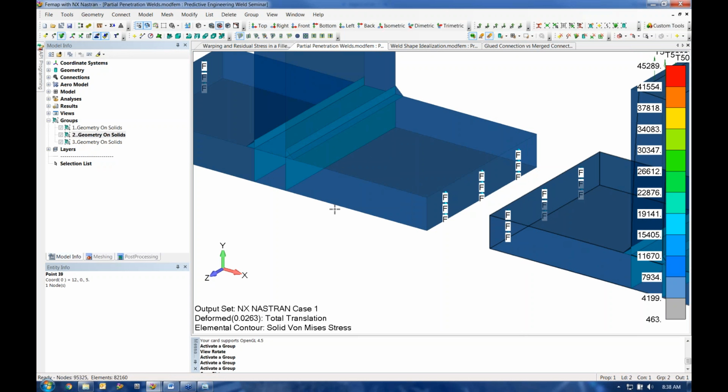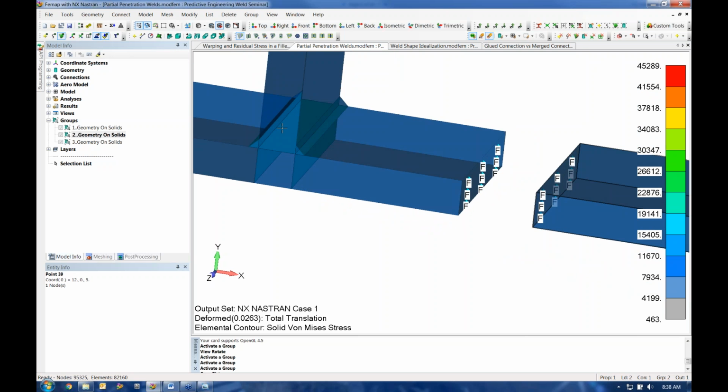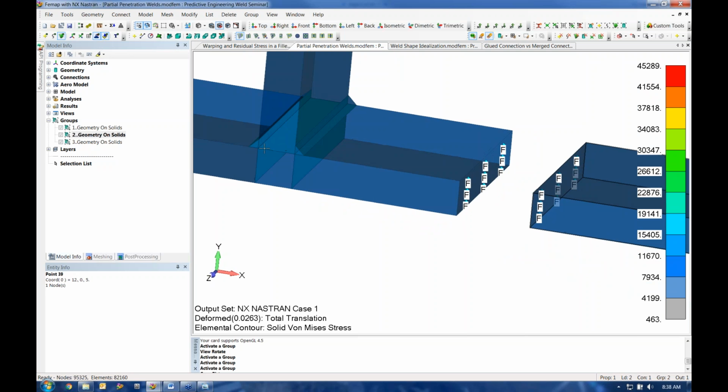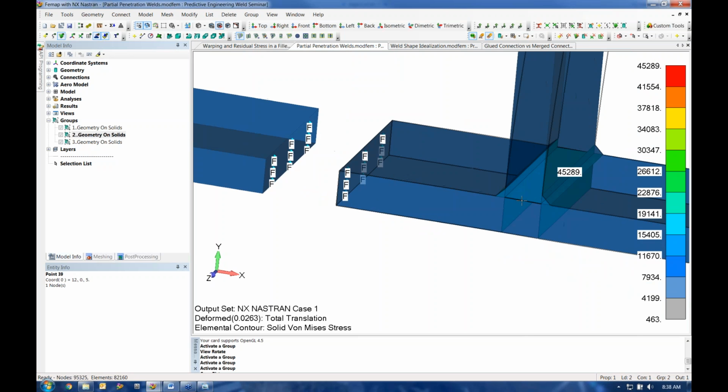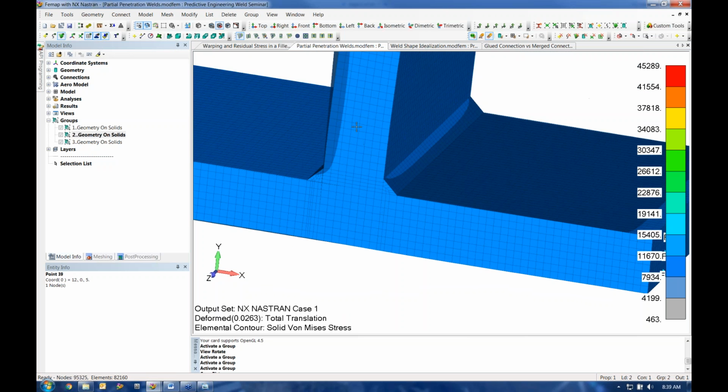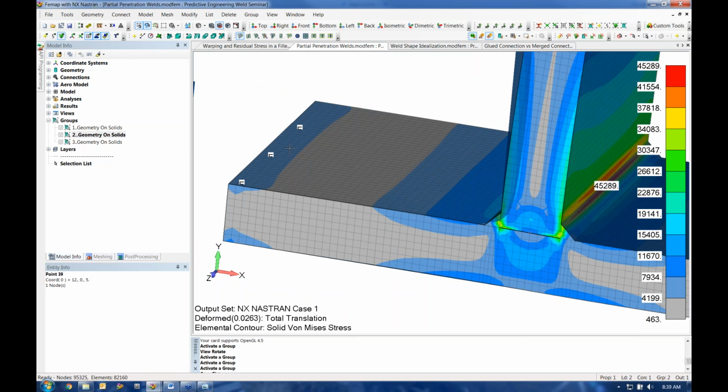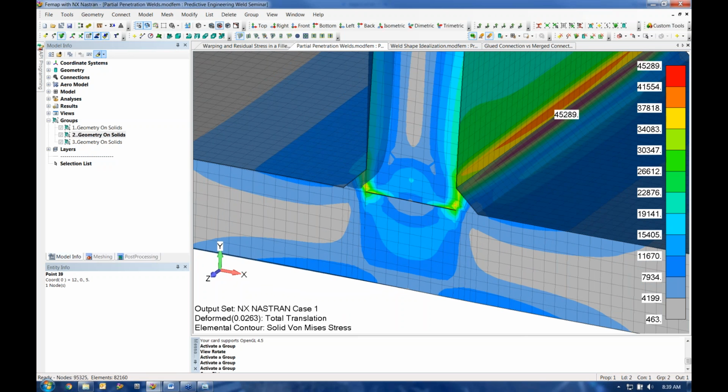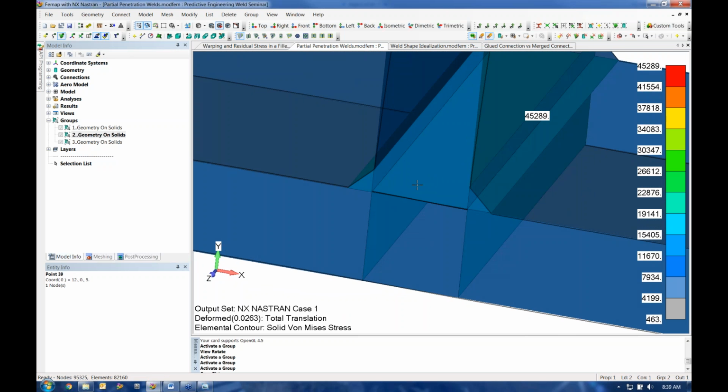These are hex mesh parts, and you're going to see a lot of hex meshing and surface meshing in this workshop. If you need more information, we can point you to some other seminars to get you up to speed on that. What I wanted to show here is that the bottom surface of this plate coming into this T-junction, whether or not the nodes on that surface get merged, is going to change the load path significantly. Here you can see continuous mesh. Here I disabled merging on that face. When you set up hex meshing, it automatically matches faces and merges nodes.